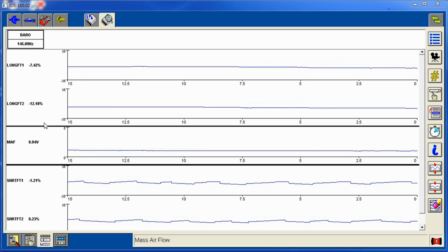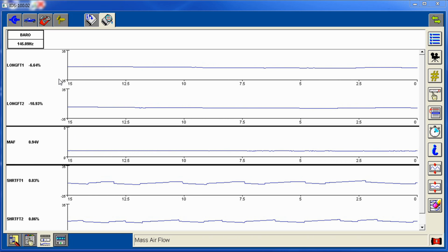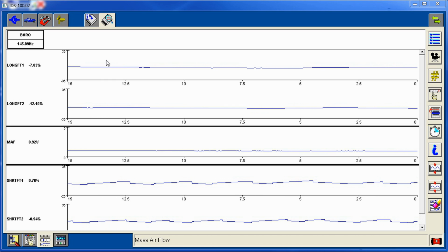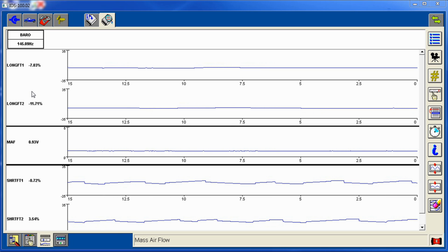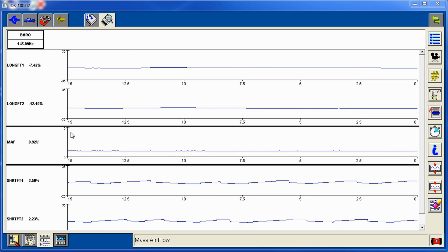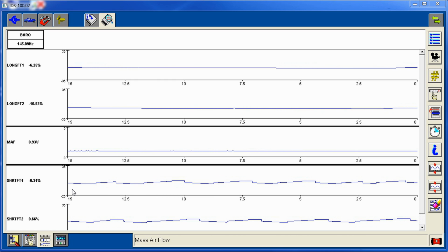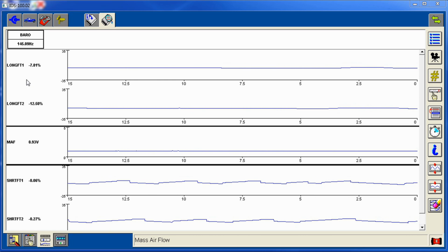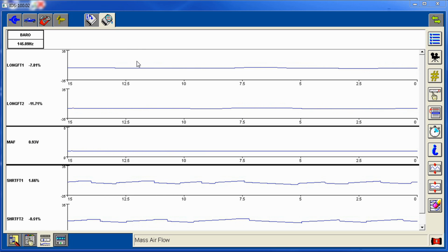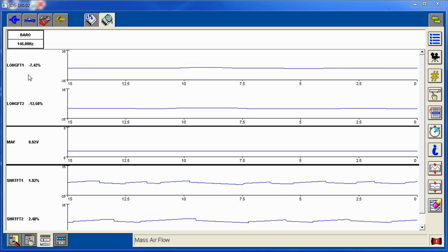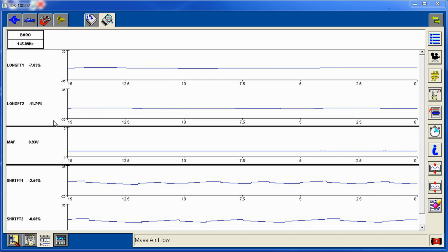So it's already bumped up well beyond what it should be for the airflow that's going across it. So it's going to overestimate at idle. As you can see here, it's pulling the fuel trims down because it's reacting to the O2 sensors. And once we go for a drive, you're going to see initially the short terms skyrocket 25, 26%, and then once it learns it, it'll do the same thing over here in the long terms, and that's the positive, which means we're running lean. Okay, right now I think it's running too rich, which it technically is, so it's adjusting the fuel trims negative. It's taking away fuel.